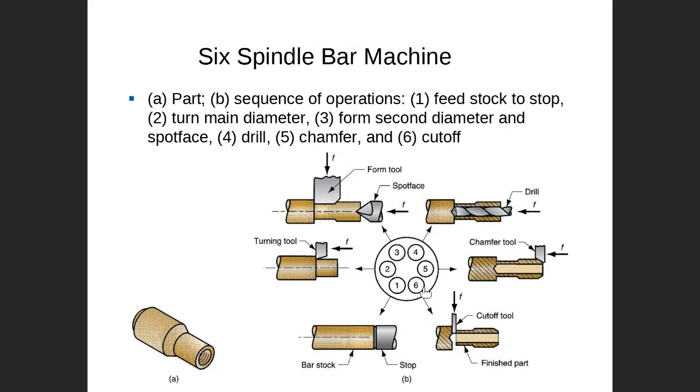We call it 6 bars. This is bar number 1, this is 2, number 3, number 4, number 5, number 6. So we have here, you can see 6 bars, and these 6 bars are actually 6 workpieces. And at every workpiece there is one tool. This tool does a certain cut, another tool, and this one is rotating. When finished, then 1 becomes 2, 2 becomes 3, 3 becomes 4, and so on, and then you get a sequence.